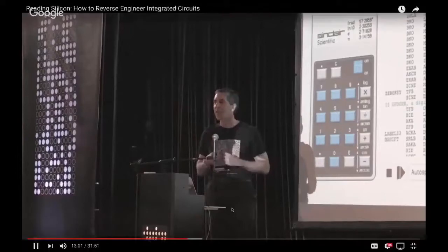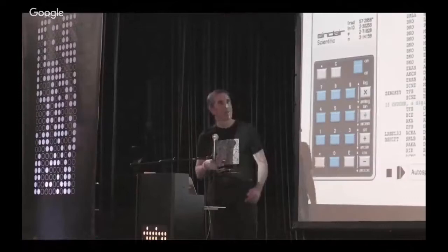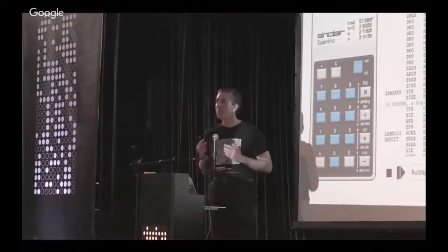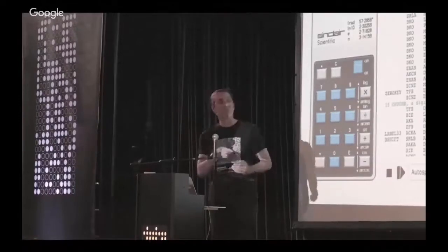Because it's a decimal calculator, dividing by 1,000 is just a trivial shift. You do a shift and then add and subtract. You just repeat that as necessary, and you can get your sine, cosine, inverse operations. One side effect of this is that the bigger the angle you put in, the slower the calculator. It just has to keep going until it gets to the angle.